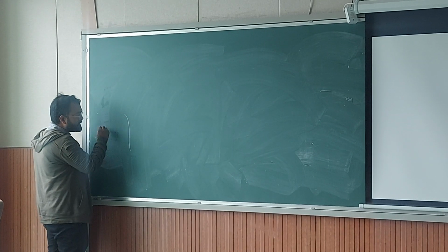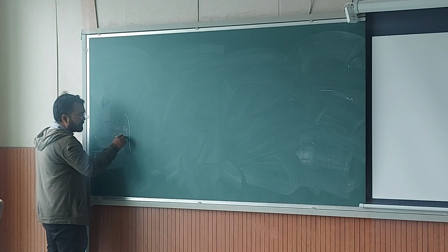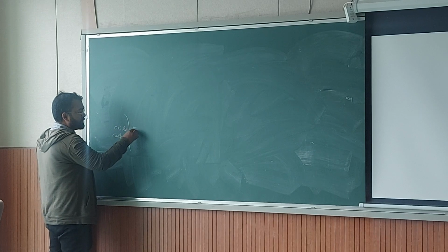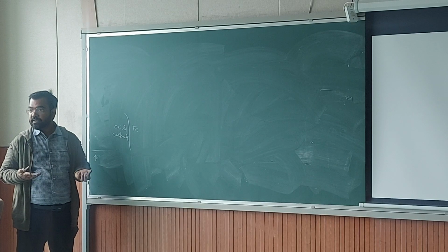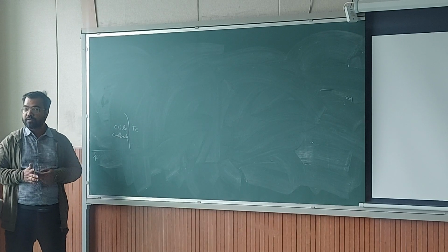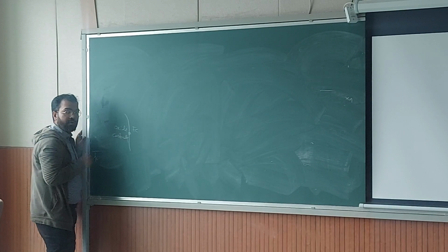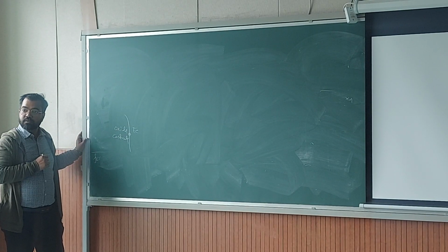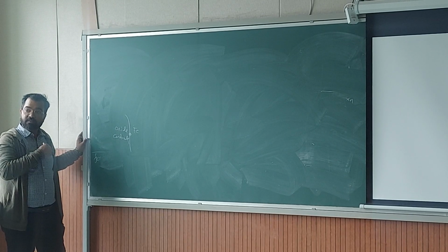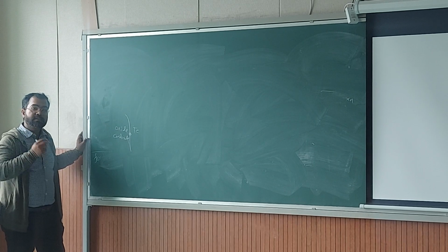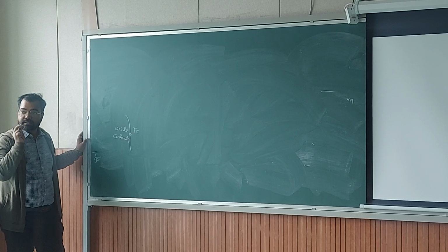inclusion, on this side you have oxide or carbide, and the other side you have steel. So steel is going to deform more, carbides are not going to deform that much, oxides are not going to deform that much. Okay, so on this point, for the same amount of stress, you will be having two different amounts of strains because of the elastic modulus of the oxide on one side and the elastic modulus of the steel on the other side. Just imagining pure elasticity.